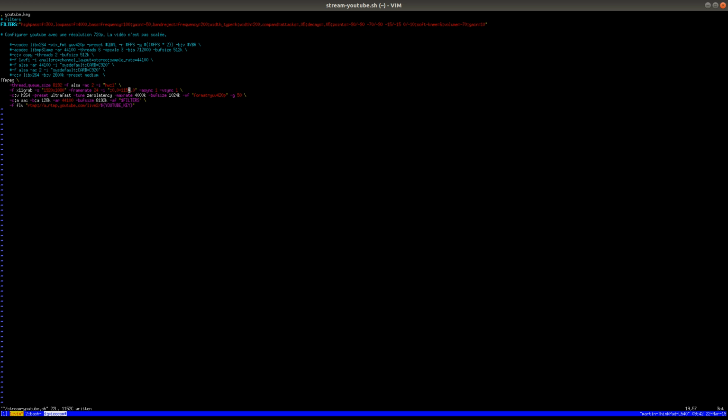Right, so today I'm going to start with coding the clock code. I'm going to be improving the RCC initialization because I think it's a total mess. In the STM32, the parts of the CMSIS that are responsible for setting up the clocks become hard to use to run the same code on multiple targets with different clock settings, with different crystals, and with different maximum frequencies. So what I want to do is make sure that the clocks are configurable from the device tree.